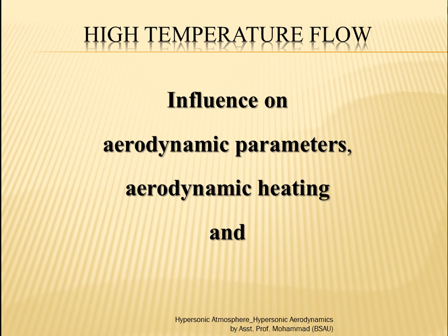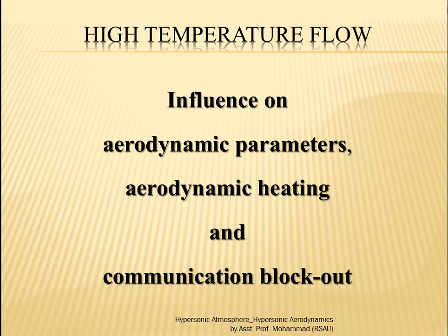So the presence of a hot fluid near the cold vehicle surface induces high temperature also, not only through convection but also through radiation. And communication waves, which are essentially radio waves, get absorbed by the free electrons, and these free electrons are formed by the ionization of the atmosphere. This phenomenon is called communication blackout, where onboard and ground communication gets terminated. So a communication problem also comes because of this ionized fluid around the vehicle, because it absorbs the radio waves.